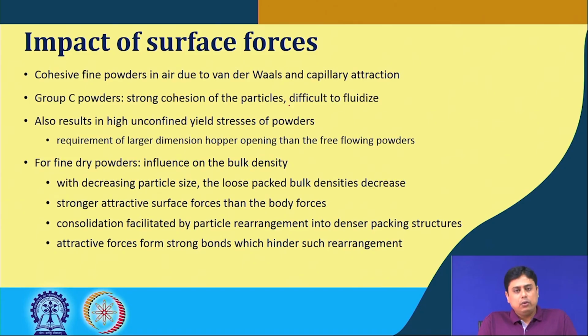It also influences the bulk density of fine powders, because the bulk density depends on the particle size. As the particle size decreases, the loosely packed bulk density also decreases, which may sound a bit counterintuitive, because by reducing the particle size one would expect more and more compact densities.